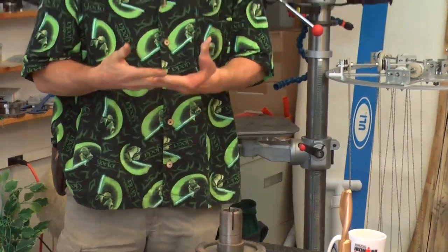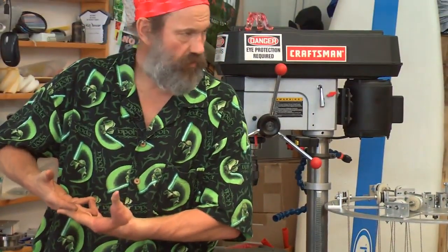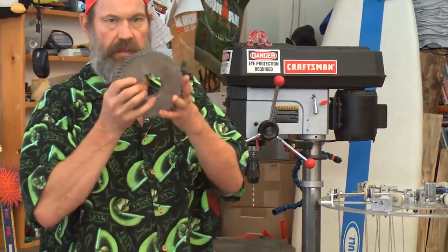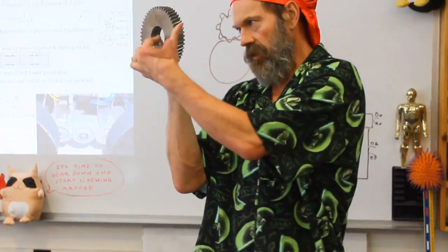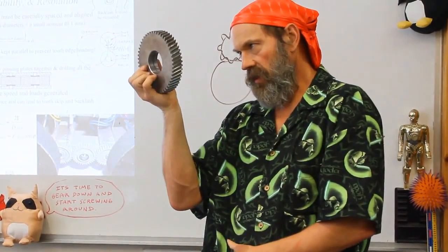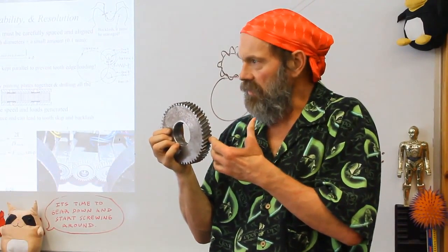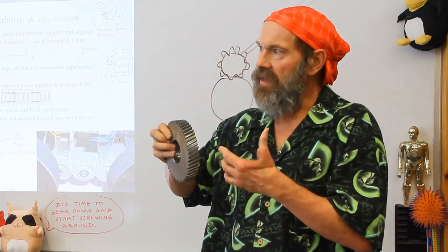But if I push them together so I have no rattle at all, first of all, this looks really round, but it's not going to be perfect. The center is going to be offset to one side or the other. And as the gear rotates, if you happen to have pushed it together at the smallest point, when you rotate it and it comes apart, then you have backlash.